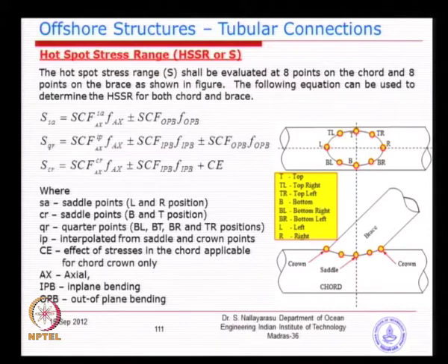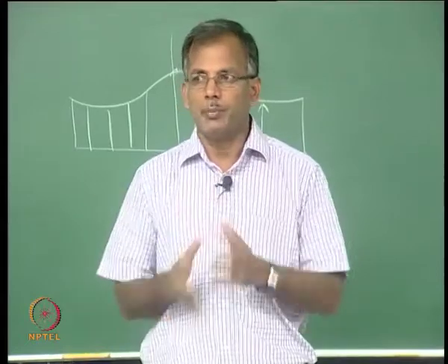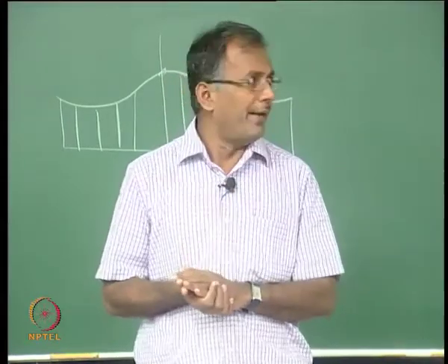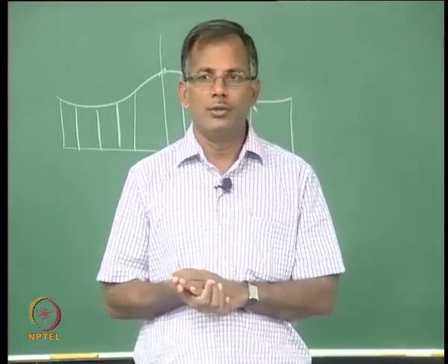So, you can calculate, but you must remember the SCF values are given only for the 4 points, left, right, top and bottom. So, you should be able to calculate by interpolation and calculate the stresses and make a plot like what I have drawn on the blackboard. So, basically this is the idea to understand how you will do it.